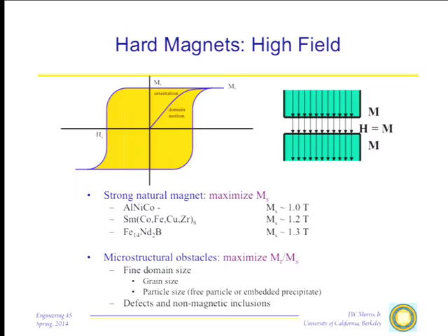Those are hard magnets. For a hard magnet, you want a hysteresis loop that looks like shown here, with a very high remnant magnetization and a very big coercive force, because you want it to be very difficult to get rid of that magnetization. I remember we used to do tests at the National Magnet Lab, which was then located at MIT. It's been Florida State for years now. They would have these big 12 Tesla magnets in which we were doing various superconductivity experiments in those days. And the first thing that you would be told, and we all forgot and all paid the penalty, is that you had to take out your wallet with all your credit cards in it and leave it about 100 yards from where these big magnets were, or you would not have credit cards anymore that anyone could read.